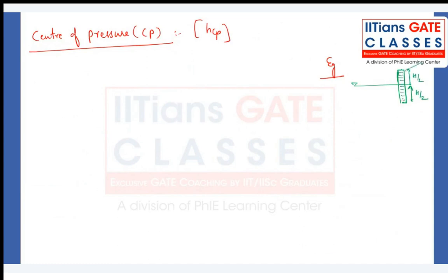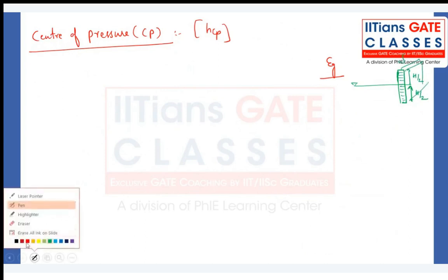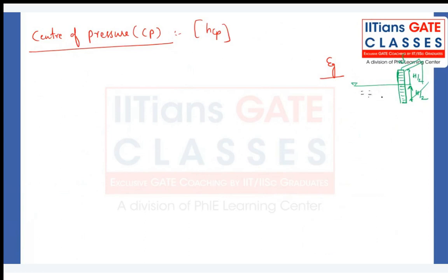Having the width, let's say whatever it may be, W. So you are talking about this case, right? Whatever the liquid is, the liquid will be exerting the pressure force, right? And that pressure force will be rho g into h bar into area, right? H bar will be in that case h by 2 by 2.